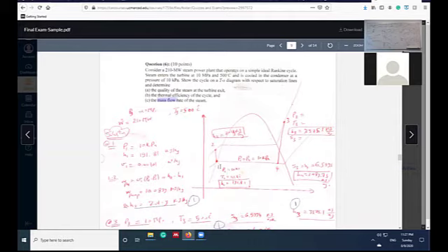In state 1, you have just a pressure. And it is saturated liquid. You can get T1, which is saturated temperature, and you get H1, you can get everything at 1. So always these cases, we start at this point, complete liquid at saturated line. So we have P1. From table A5, you can get T1. Saturated temperature at this pressure, 10 kilopascal.